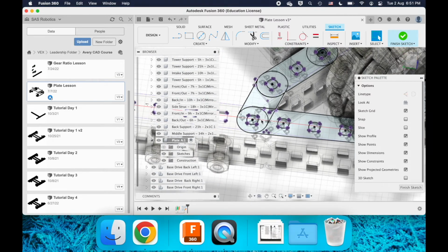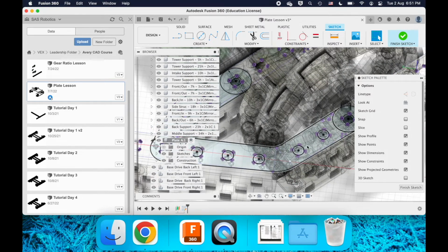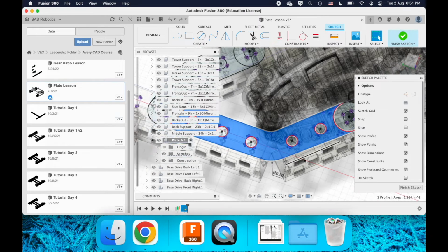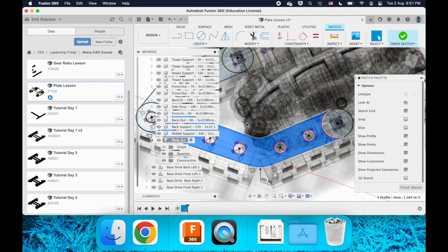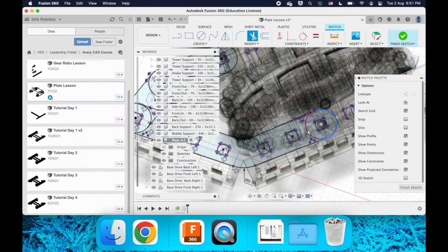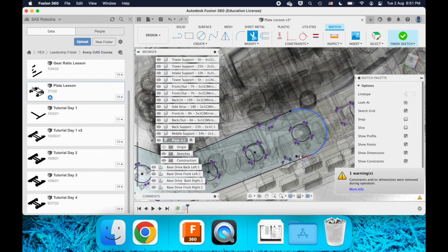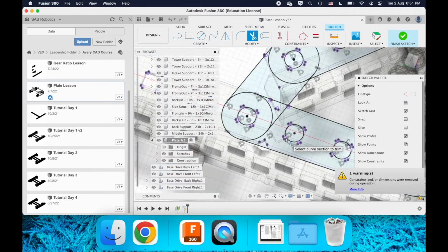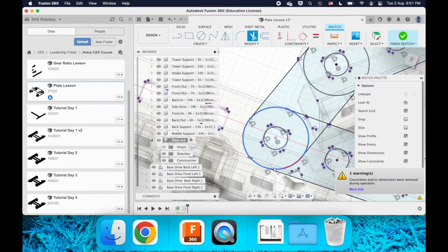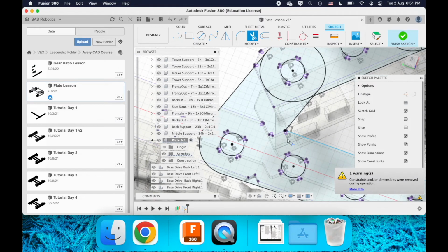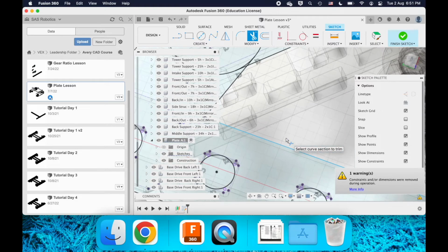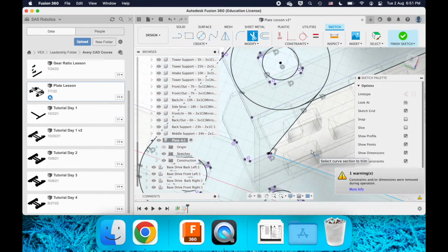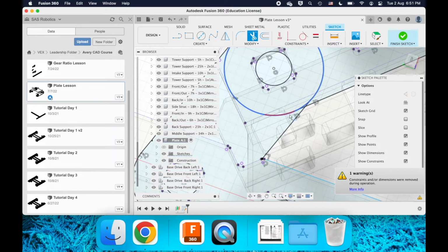Okay, so I got around a corner there. Something else is, if I select this surface, right, it's not all connected. That's because we have a solid line here, so I'm going to trim away some of the dead weight. Like, we don't need these lines here. You want to cut them away whenever you CAD plates like this. Cut away all your unnecessary lines. As you see, also cutting away lines can make some of these lines no longer constrained. Problem in and of itself.